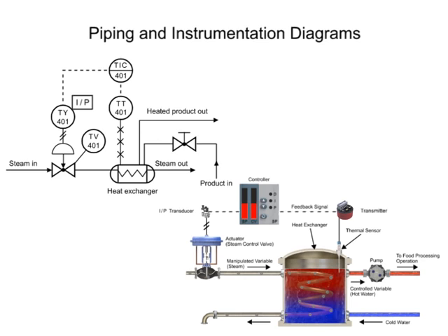Identification of the control loop is notated by the tag number 401 within the balloons. The valve that allows steam to flow through the pipe is the symbol with two triangles. In the top portion of the symbols is the functional identifier, and the first letter denotes the measured variable. The first letter of each functional identifier is the letter T, which defines the process of temperature control.